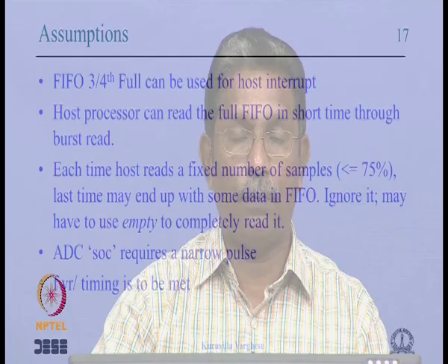So the question is, what is the next step, and can we go to the control algorithm, the state diagram? No, I think the very important thing is that we have to draw the timing diagram, the input and output relation from this description.